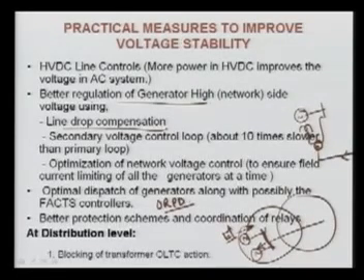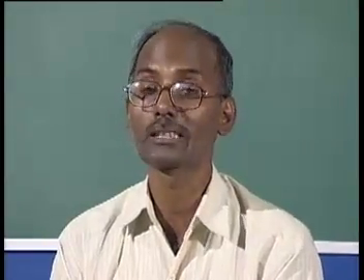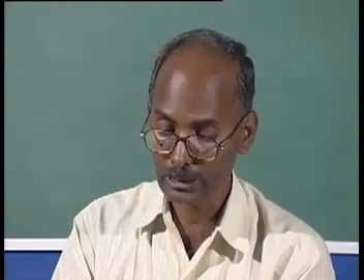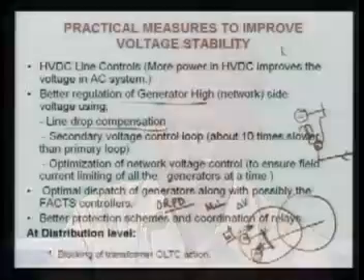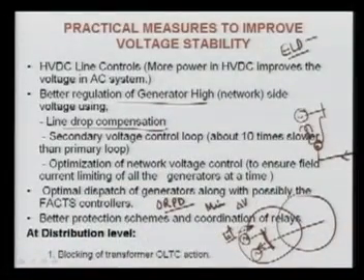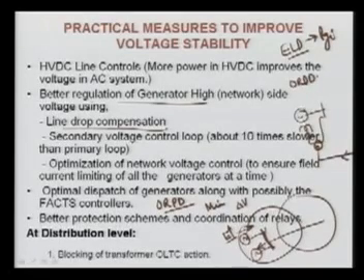where we minimize, again the minimization may be any objective. Minimization may be of the voltage deviation. Minimization may be of the loss, subjected to various constraints. Those constraints are your real power limits. Again, we are not touching the real power limit, because economic dispatch, called ELD, economic load dispatch, is where we set the real power generation output. However, in ORPD, we are setting the reactive power generation of the generators.